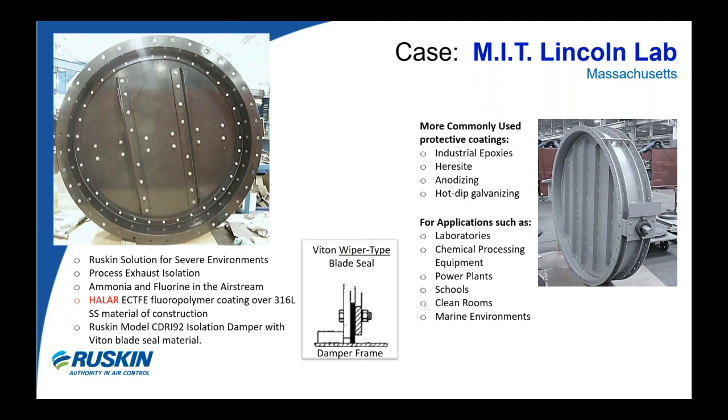The extreme corrosive nature of the airstream required the damper to be fabricated of grade 316L stainless steel and finished with Halar ECTFE fluoropolymer coating. This coating is applied using a fluidized bed coating process, which creates a finished product with optimum chemical and thermal resistance, while also creating a very smooth surface, which is compatible with the operation of the Viton wiper blade seal.